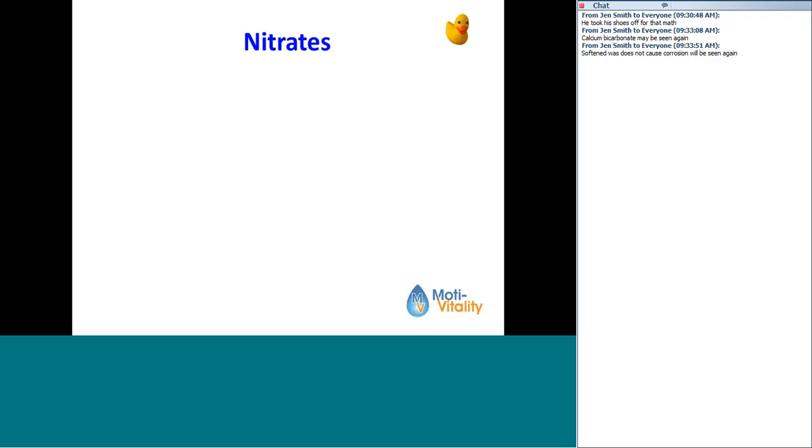What we're talking about mostly today is an anion resin that's going to remove the negatively charged ions. If it's removing anions, we know that the resin itself has to have a positive charge so that it can take out the negatively charged ions in the water. That's what we're talking about when we're removing silica or nitrates. Those are anions, and you can put an anion resin in that will take them out.